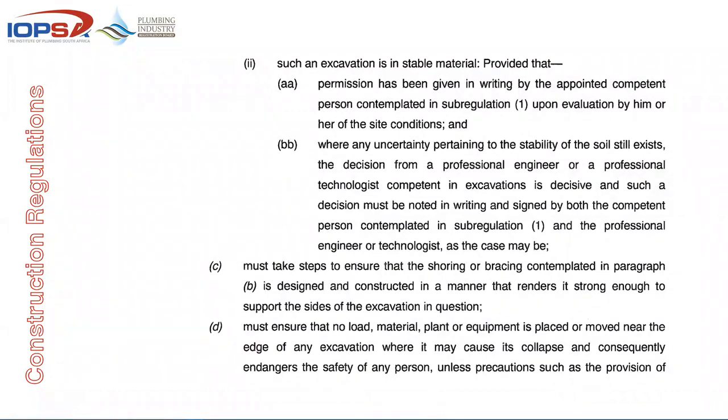In an excavation in stable material, permission has been given in writing by that appointed person after evaluating the site conditions, where uncertainty pertaining to the stability of the soil still exists. The decision from an engineer or a technologist competent in excavations is decisive, and such a decision must be noted in writing and signed by both the competent person and the professional engineer or technologist, as the case may be. In other words, it's not simply a case of, it looks alright to me, let's get into this, and then we're up and running.